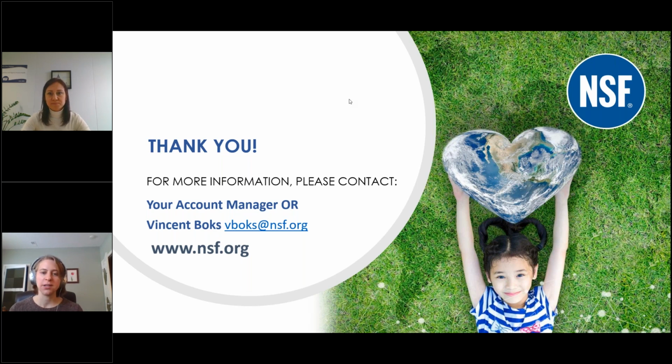That standard is concerned not with lead leaching, but with the actual lead content of the wetted surfaces of a given faucet. For that standard, we're simply doing a lead digest and determining whether the lead content of the wetted surfaces meets a maximum weighted lead content average of 0.25%. So that's not affected by these Q criteria reductions.